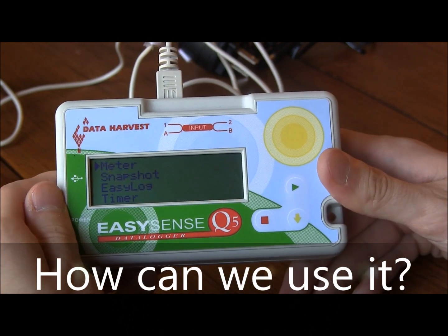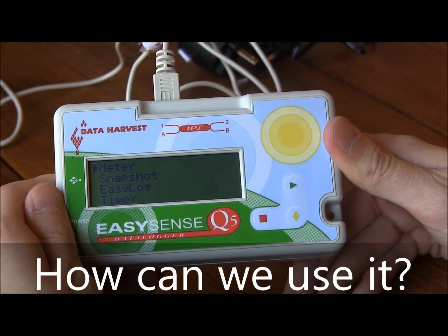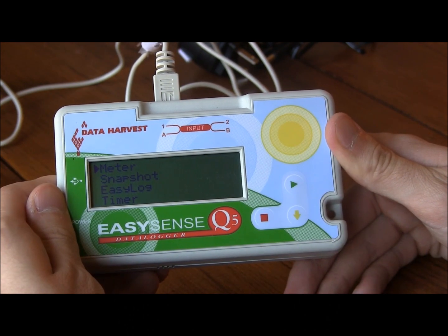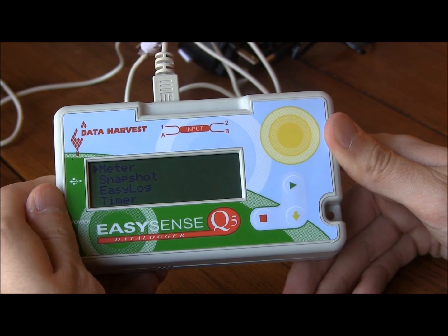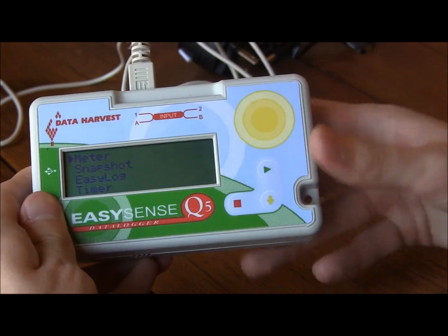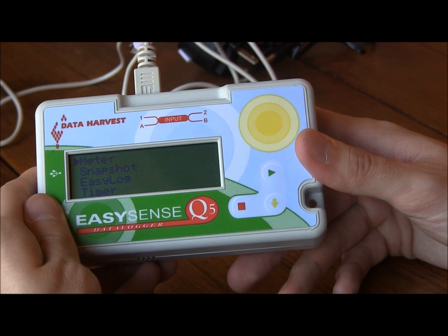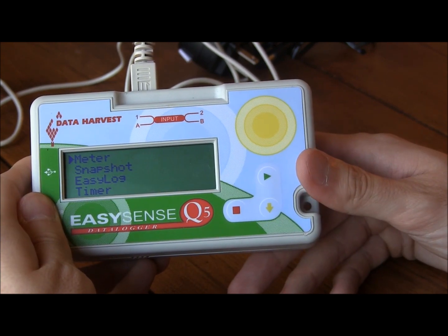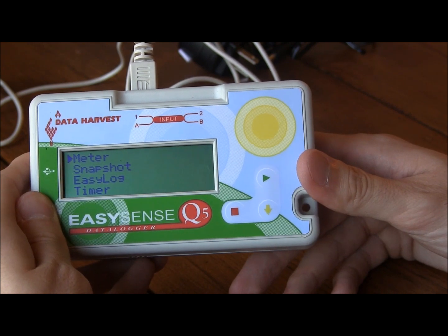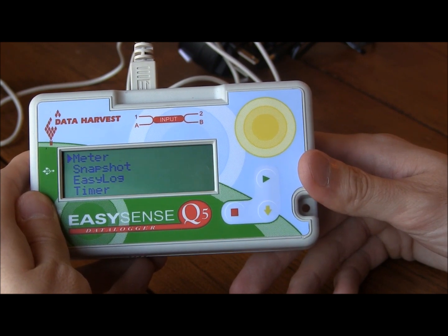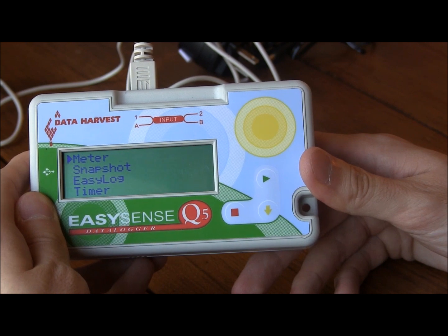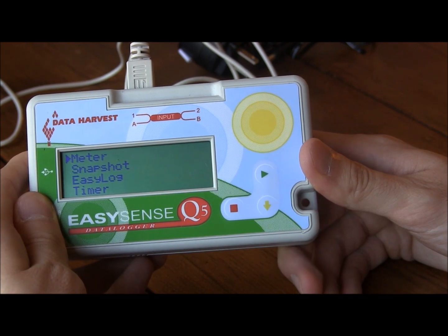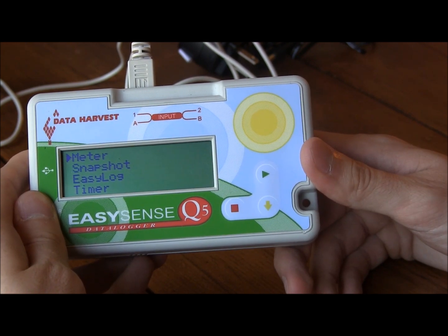There are 3 different ways that you can use your data loggers. The first is to record the information directly onto your computer by linking your data logger to a computer with the USB cable. To do this, you'll also need to upload the EasySense software from the CD that is included in your TDSB Heat in the Environment kit. Alternatively, you can download the software from the EasySense website.